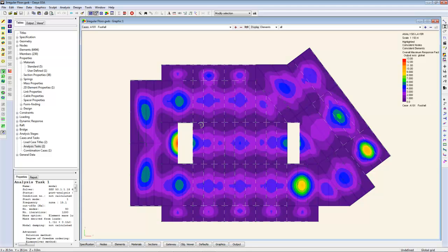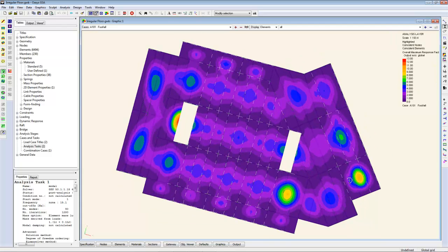Now, if we were doing, say, an operating theatre, operating theatres are interesting cases where they're very strict on the vibration, but because of the nature of the environment, people tend to be walking around slowly in them, which means the impact forces are lower. But there could be a corridor outside the operating theatre where people are in a hurry. So let us suppose that this corner down here is going to be our operating theatre.